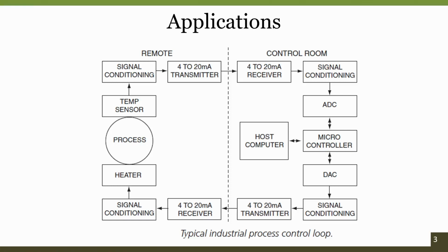when you look into the sensitivity of those sensors, it will be very small, somewhere in the range of 10 millivolt per degree centigrade, right. Such small voltages, when we directly interface to the ADC, the major problem would be accuracy: you are compromising on the accuracy, or the resolution, of the system.